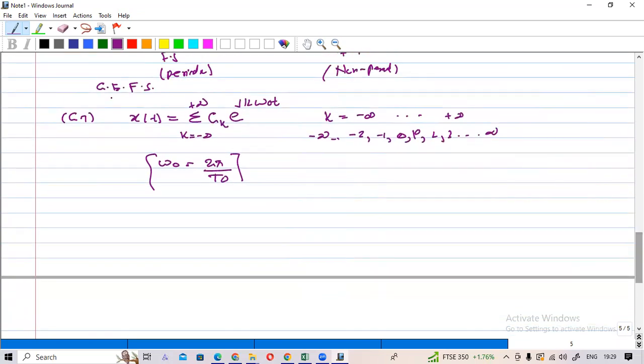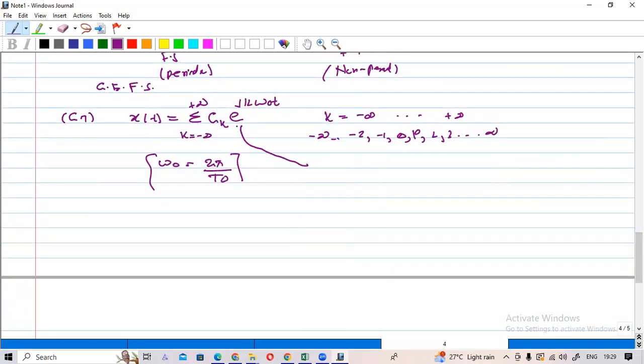You know that corresponding to each complex exponential term there is only one frequency component, and that frequency is multiplied by k. So there are different frequency components. We can represent the signal as a summation of these complex exponential terms and find the frequency components. Each one is one harmonic. Using this, we can represent any signal as a collection of harmonics.